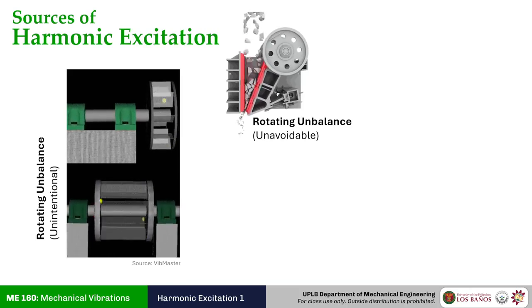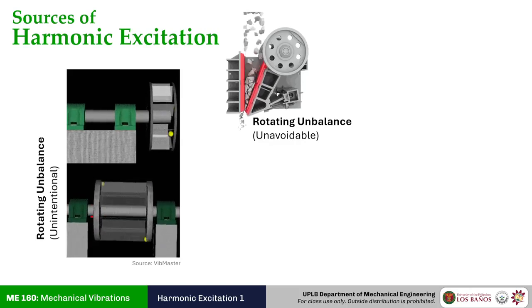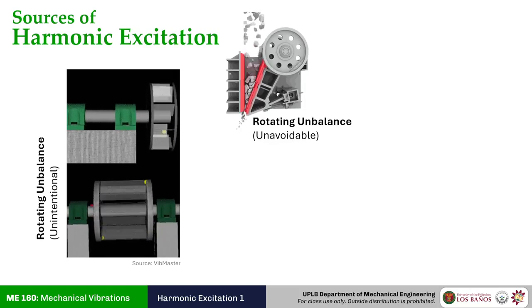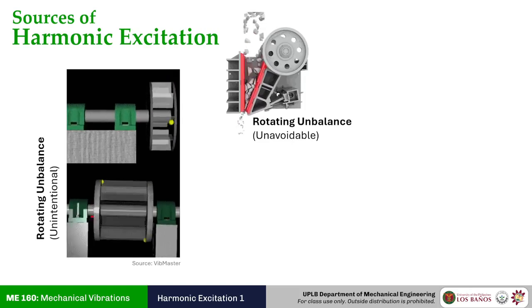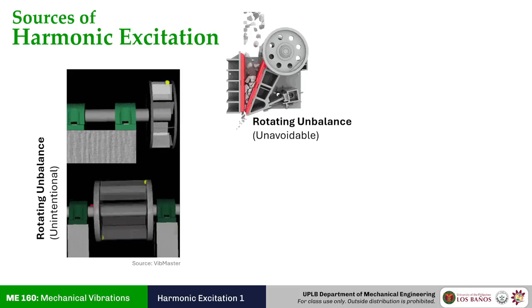There is an unbalance per cycle caused by the up and down motion of the piston. It's part of the process, part of the function. You don't want to get rid of it because that is why you employ it. So rather than eliminating the piston, you do everything that you can to mitigate the vibration from the pistons themselves.